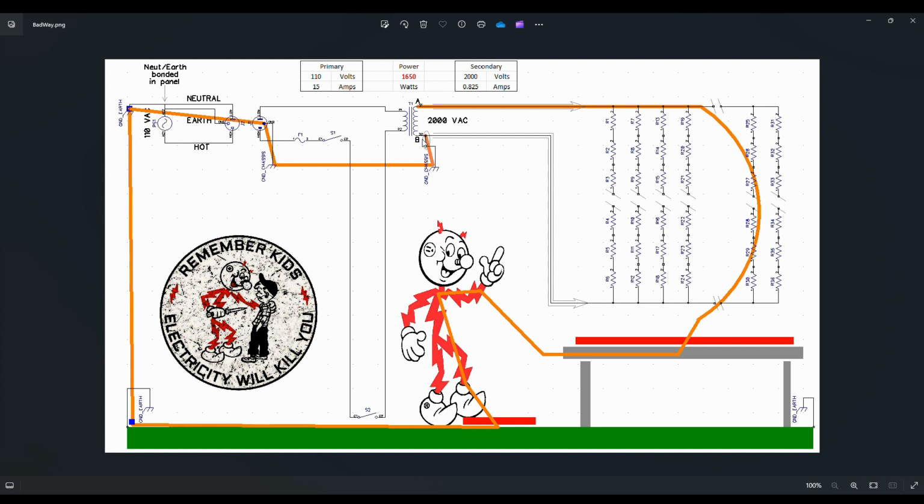However, if you have a plastic case and you have made a connection directly to your neutral coming in through a piece of wire, and you've got that piece of wire inside your plastic case, you are inviting these bad currents to return through ground, because you've now made ground available to them. You've made ground available to terminal B, which is trying to pull these electrons in as hard as it can. As hard as terminal A is trying to push them out, terminal B is trying just as hard to find some way to get them back home. So, I hope that made sense.